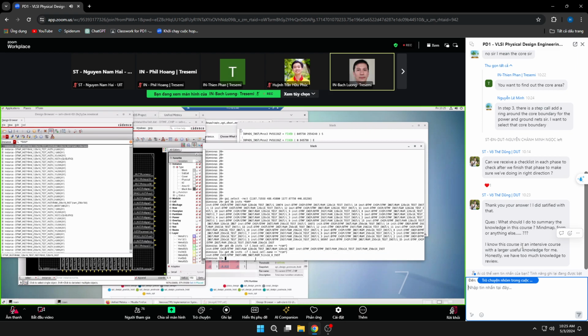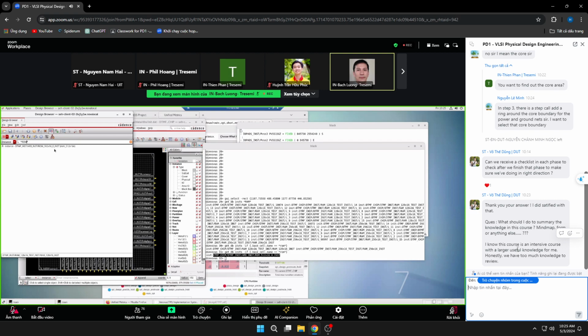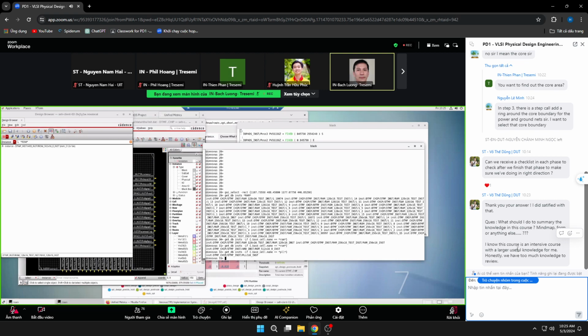You get the instance name of the ROM here. See, the instance name would be from here, right? You can do it here also. You can do ROM, and this happens to be only one ROM. There's no mux along with it, okay? And there's also another macro, a PLL macro. So here's the PLL instance, right? You can do it up here also. Just do PLL and it should come back. Okay, so that answers your questions on finding the instance.